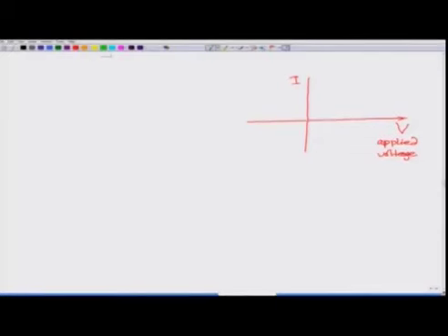When the potential is small, then generally the current is very small and almost difficult to measure, but then when the barrier height is considerably reduced, suddenly a lot of majority carriers will start diffusing and therefore, the current suddenly increases like this. Now, at what point do you see this visible increase in the current?